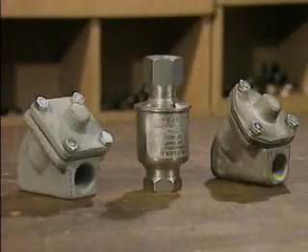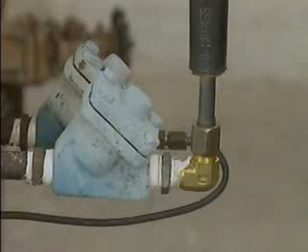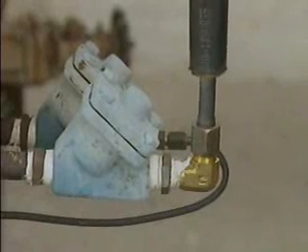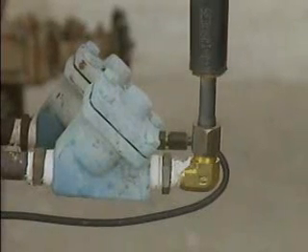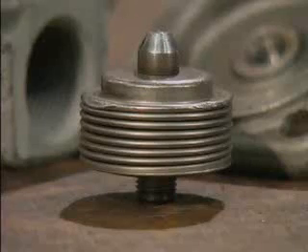In this part, we'll look at the operation of thermostatic steam traps. A thermostatic trap operates in response to the differences in temperature between steam, condensate, and air. One of the most common types of thermostatic traps is a bellows trap, which gets its name from the thermostatic bellows that is the trap's main internal component.